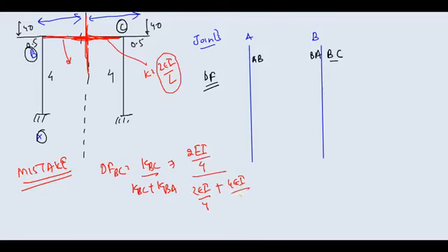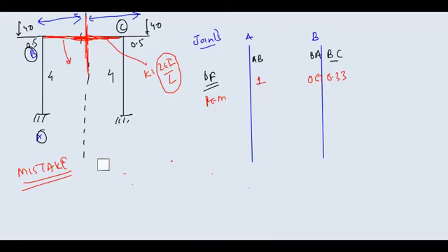KBA is normal, it is 4EI by L. So you can find out these values. I think it will come out to be 0.67. Okay, 0.67 here. This is obviously 1 and 0.33 here. Next step is your fixed end moment. Okay, I am writing these values. So be very careful what stiffness value you have to use where.